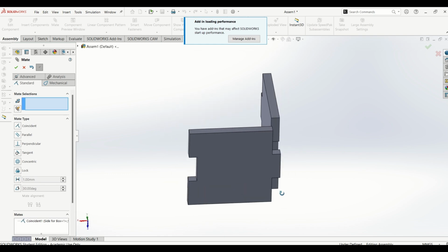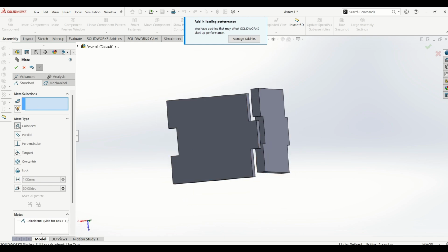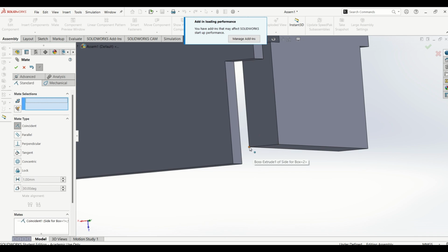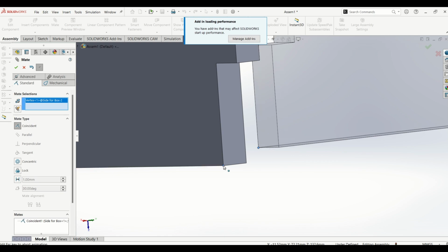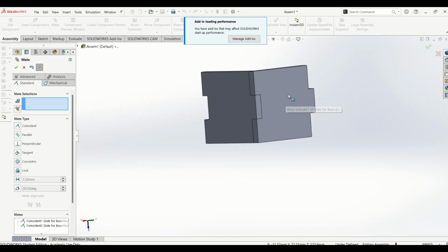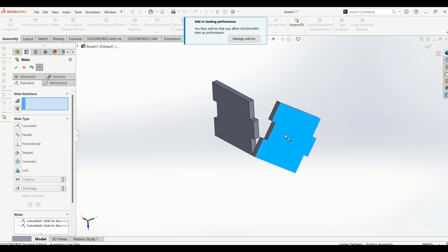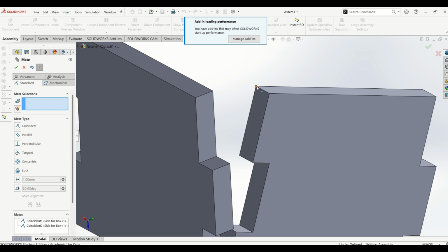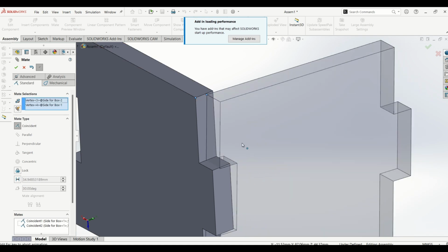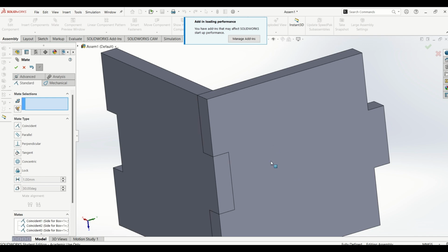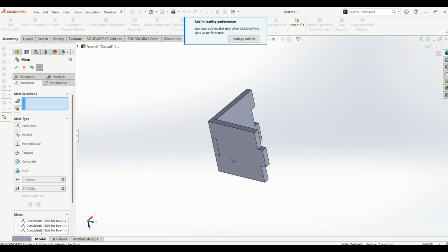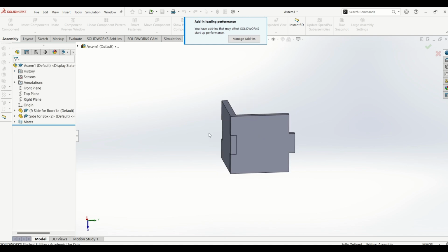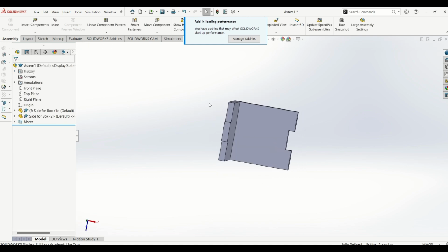What we need to line up is our corners. So we're going to click coincident again. Click that corner, and we are going to click the corner we want it to be lining up with, which is that one, too. Now we just check it, so it's very nearly there. We just have one more mate to make, and that will be here to here. And that should be everything stuck together, working together, and it should not move. Whenever you're done mating each part, click the green tick.